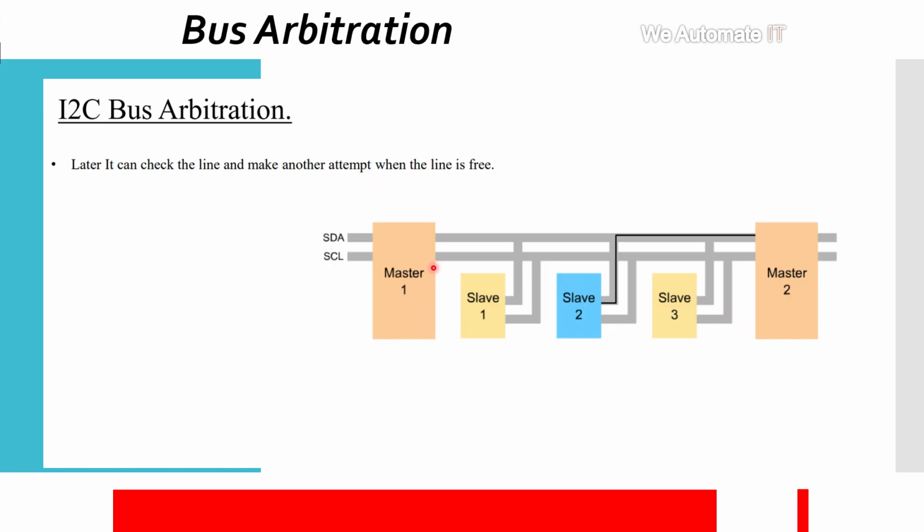When the master sends a message to all the slaves, it will send the message along with the address of the slave. While responding to the messages, first the slave will observe all the messages from the master to confirm which slave should respond, with its unique address. If the address matches, only then will it send the response back to the master. So again, address-based communication, that is what I told you.